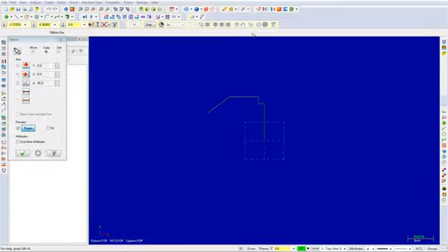Enable Copy and enable the radio button to mirror about the Y-axis with an X reference point of -2.2. Now press Enter on the keyboard to see a preview of the result on the graphics user interface as shown. Select the OK button to exit the command.